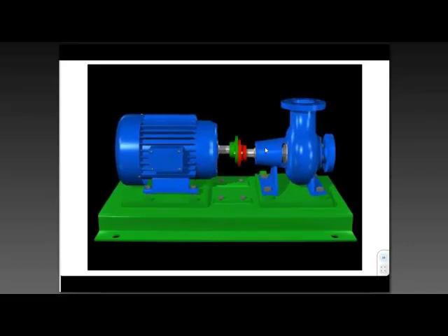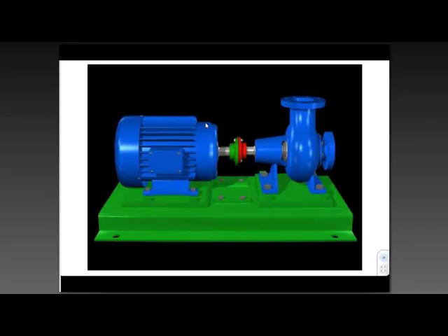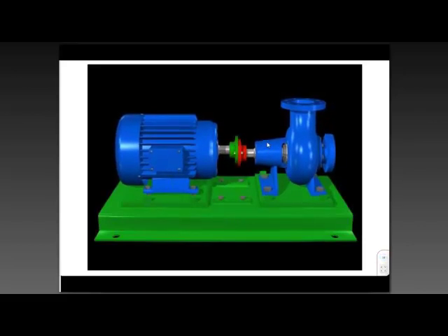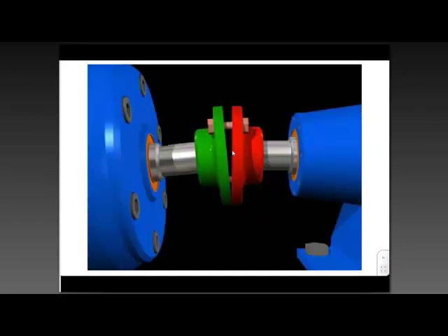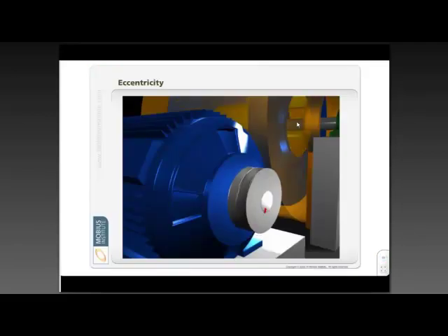There is a 180 degree phase difference from this point to this point. If it was angular misalignment, although I don't show the motion here, we create axial forces, which means if I compared the phase from here to here, I would see that they are out of phase. And there's special precautions you've got to take with phase readings, but now's not the time.